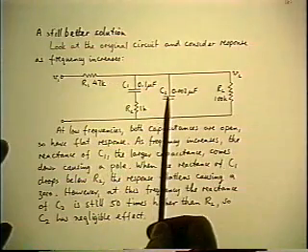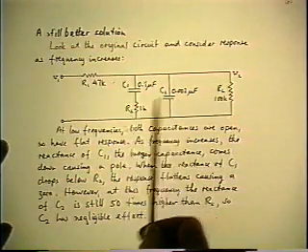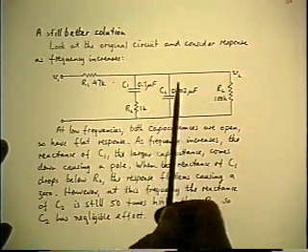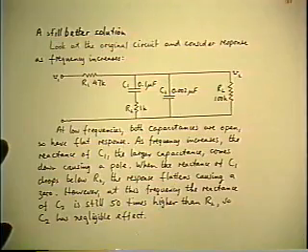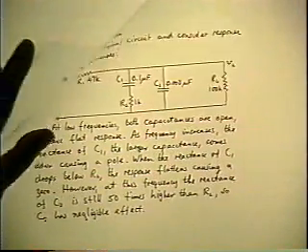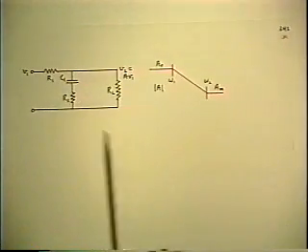Finally, at a still higher frequency, the reactance of C2 comes down to be about 1K. Then it causes the gain to fall off again. From its already lower value, it falls off even more. But only C2 is doing anything in that frequency range. So you see right away that you can divide the result into two separate frequency ranges.